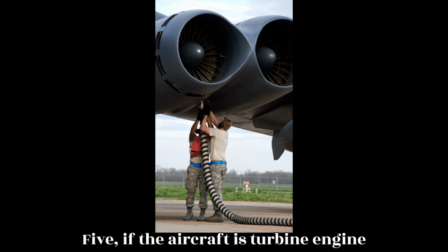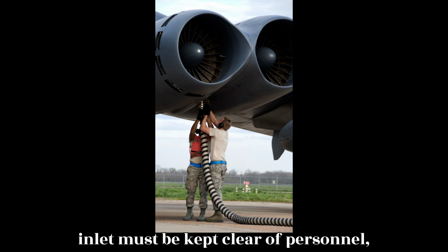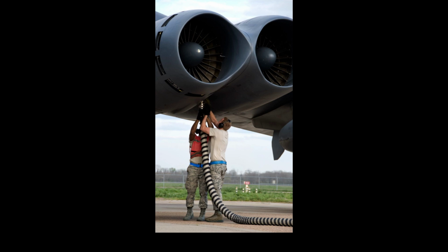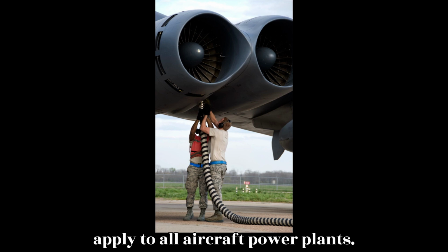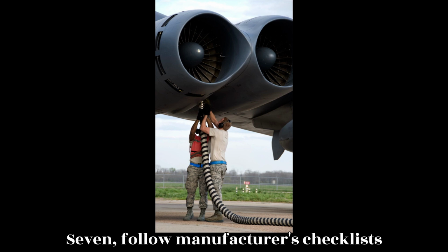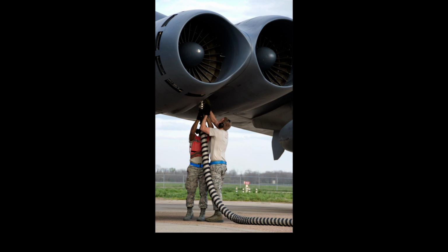5. If the aircraft is turbine engine powered, the area in front of the jet inlet must be kept clear of personnel, property, and/or debris, FOD. 6. These before starting procedures apply to all aircraft power plants. 7. Follow manufacturer's checklists for start procedures and shutdown procedures.